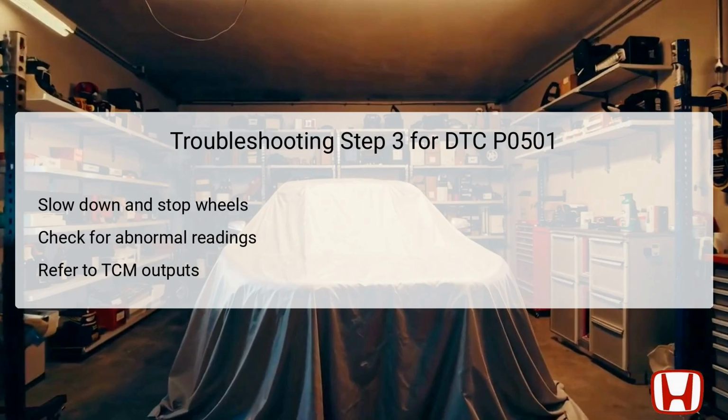It's important to closely monitor the outputs from the TCM to check for any discrepancies between expected and actual performance. Understanding whether the TCM registers a proper speed from the CVT speed sensor at this point can help pinpoint whether the sensor is operating correctly or if further investigation into the sensor or its connections is needed. This thorough checking is a critical process in ensuring that no underlying issues are missed.